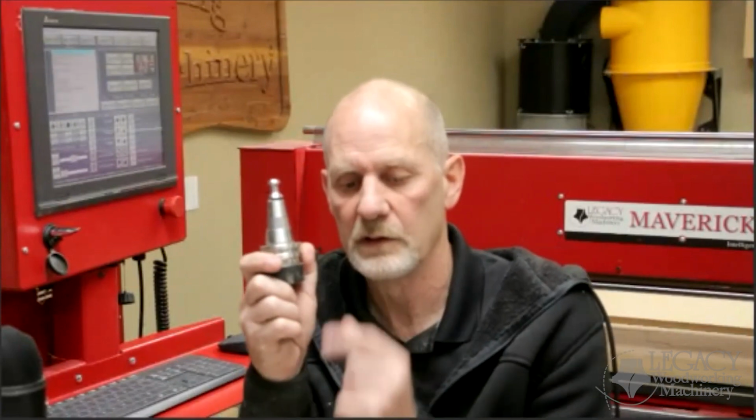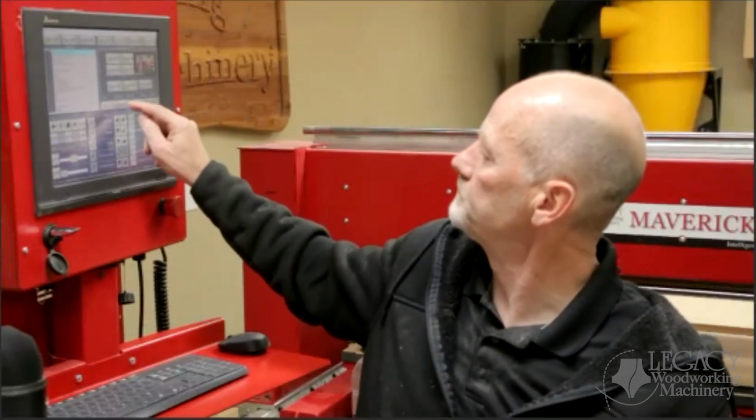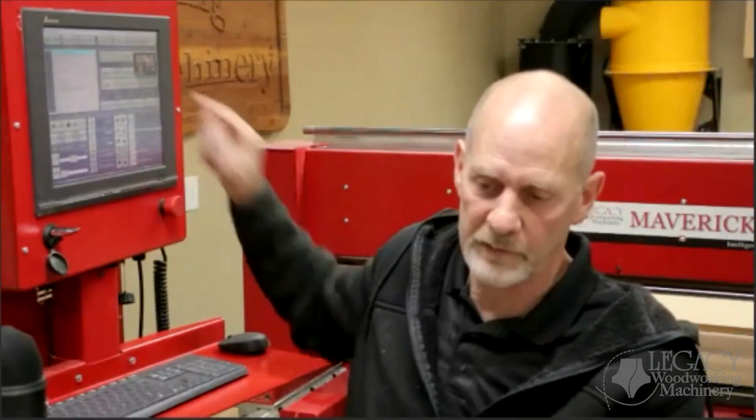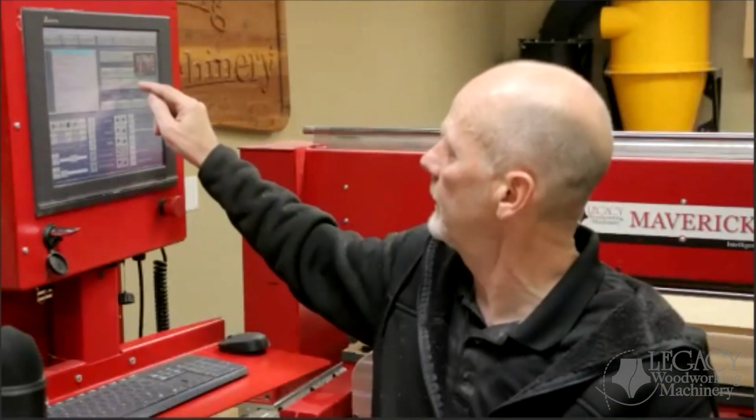Now, in a manual tool change system that does not have the tool holder, you can't do this. You're just going to have to set it, give yourself a window. But in an auto tool change like this system, you can put your longest tool in here and then run it. So you remember that button I had on the screen, which was set rapid Z. It's right up here. When I click that, it's going to ask me which tool to use. So I'll go ahead and click that.